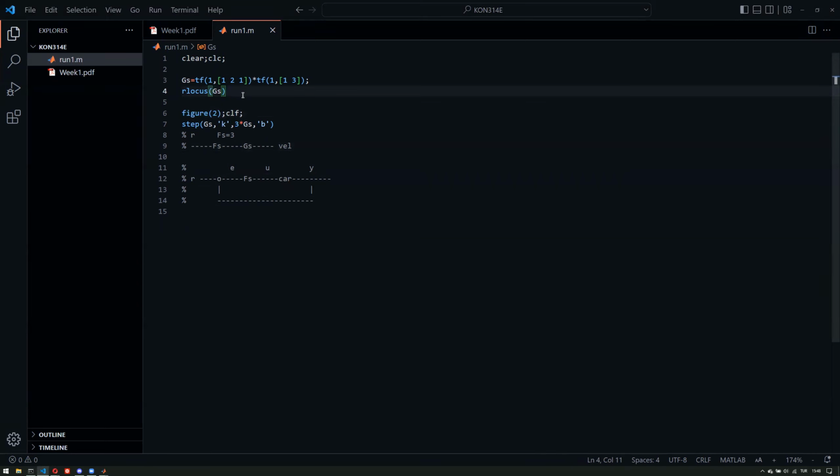And root locus focuses on the most basic structure for Fs, which is basically just a static controller. By static, I mean it's just a coefficient. So we are looking for the ideal coefficient that can be used here, which is basically the relation between the error and the control input, or the system input. So we're looking for a connection between the velocity reference and the velocity of the car, the difference of that, and the gas pedal angle. So we try to come up with an ideal coefficient for Fs so that it works better in closed loop, or works at all.